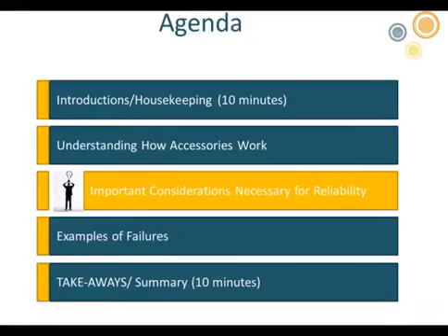So you may see that, and if you see that, that's nothing to be alarmed at. It will show up as a slight hot spot, and I have seen it show up on some infrared studies, but that's very typical to see that little bit hotter temperature there, and it doesn't affect the performance of the termination or the life of the termination.